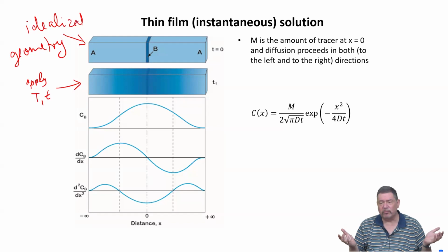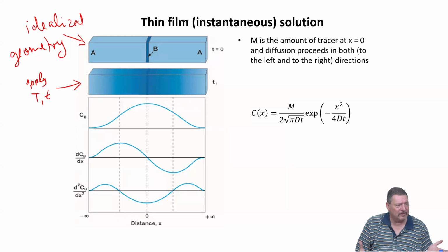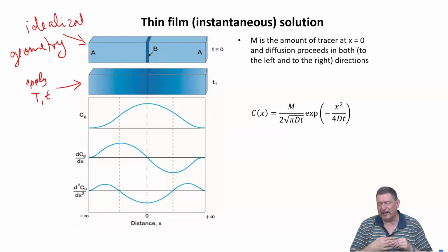Temperature, again, you go probably to temperatures around or above half the melting temperature of A, so that diffusion becomes measurable. You wait for a certain time t, and for an experiment, we never know before the first test experiments what is a good time to wait. This is the experimental finding.